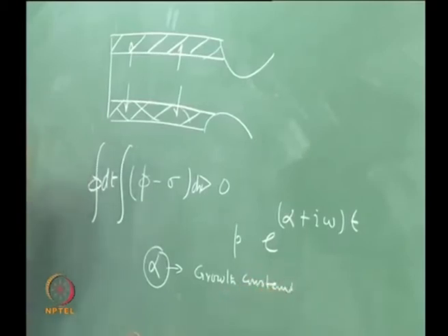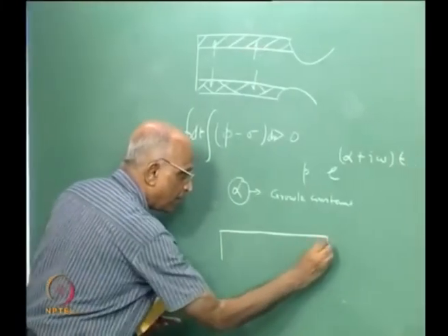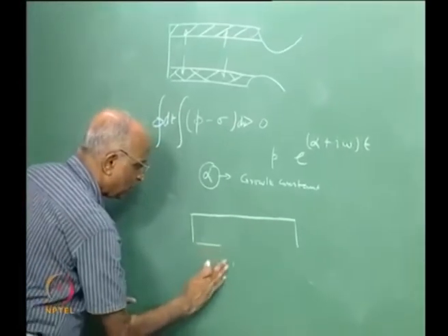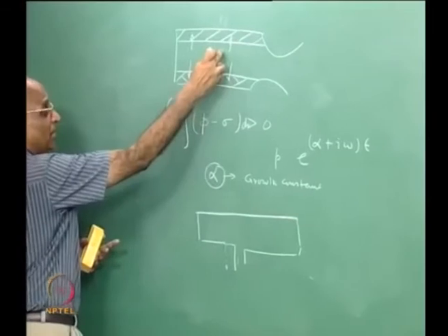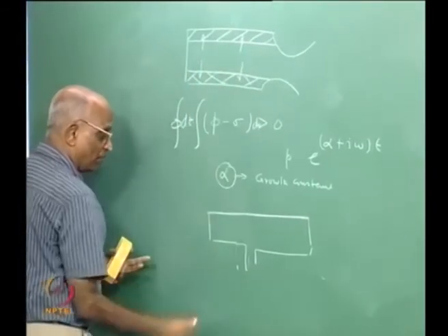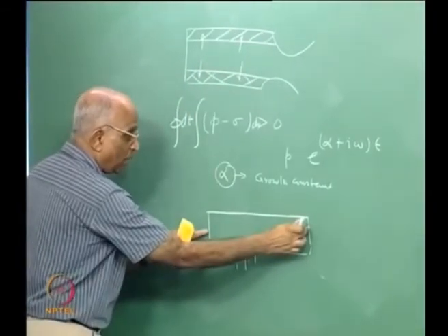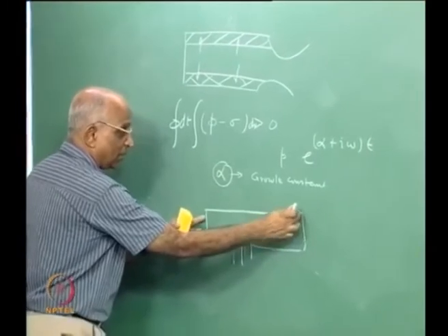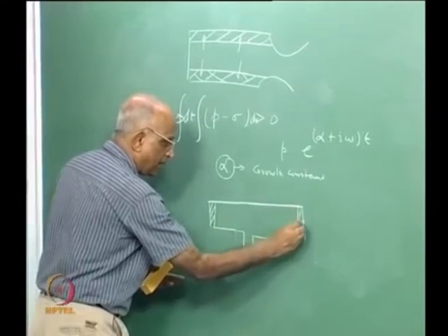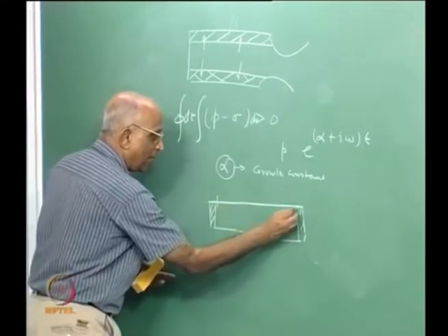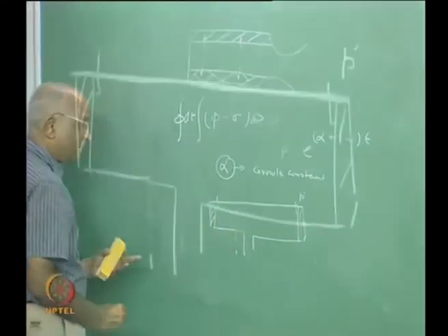To be able to measure this, I make a tube. I make the length of the tube such that I am getting the same frequency as my chamber over here, the standing wave mode of the chamber. In the fundamental, this length gives me this frequency. I put a slab of propellant at the end, that means at the pressure antinode. I can get the precise value at the pressure antinode.